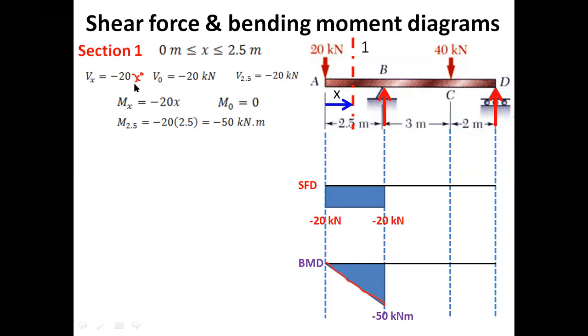The shear force equation here is 0 degree, and the bending moment equation is 1 degree. Remember that the bending moment equation would always be 1 degree more than the shear force equation. Here, this is a 0 degree line. The 0 degree line is a horizontal line, and a 1 degree line is a linear equation, so if we plot it, we would have a linear line.